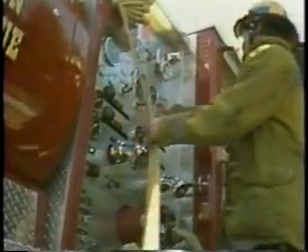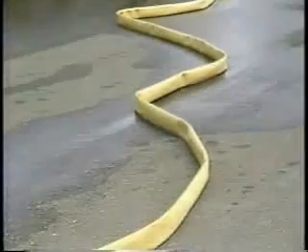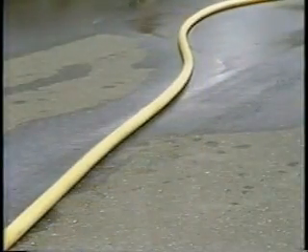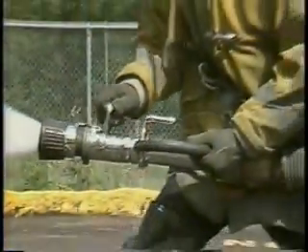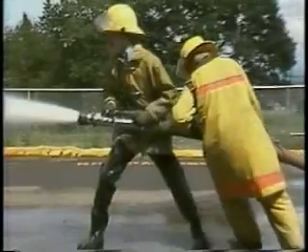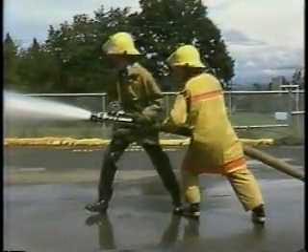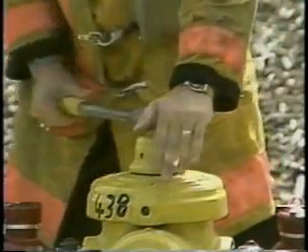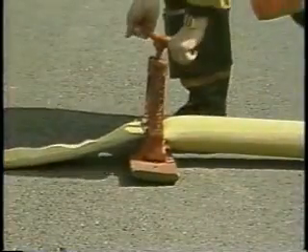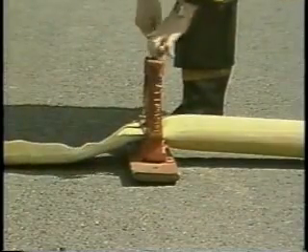When a hose is charged with water, two hydraulic forces come into play. The hose tries to straighten itself out, and when the nozzle is opened, the pressure applied by the apparatus pumps creates a recoil effect which can be difficult to control. Use safe working principles, letting your arms and legs do the work if you have to maneuver a hose to prevent back injuries. Every step of the way, water valves should be opened slowly from the hydrant to the pumps to the nozzle to prevent serious damage to the equipment by water hammer.